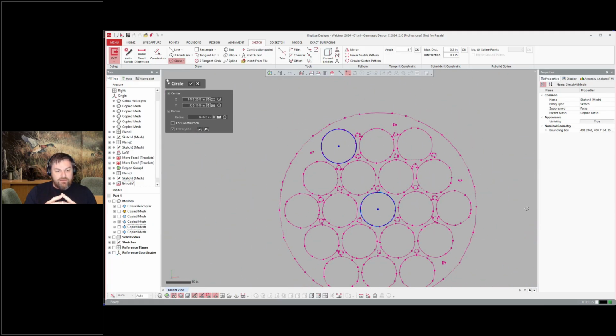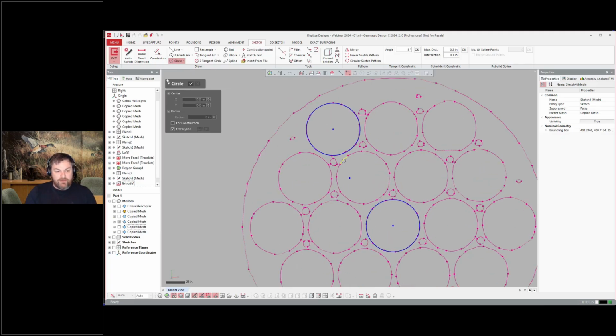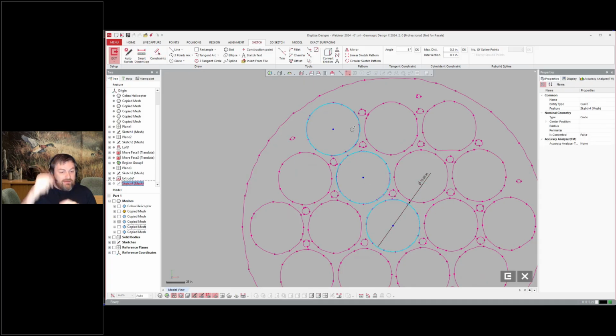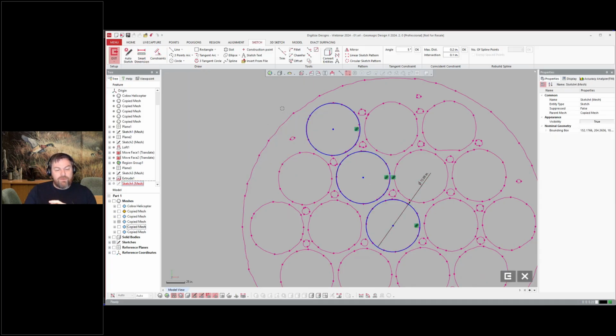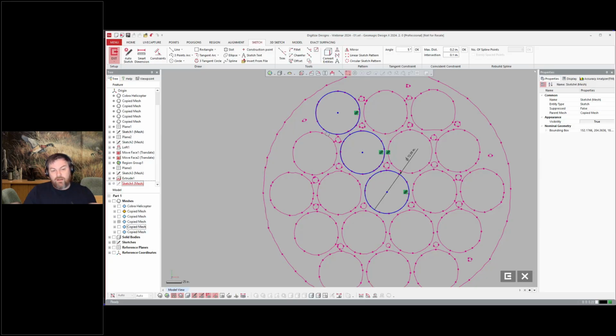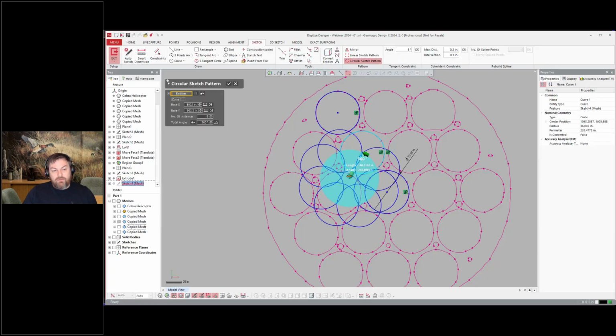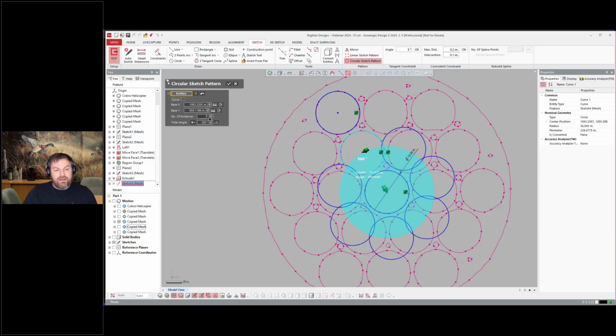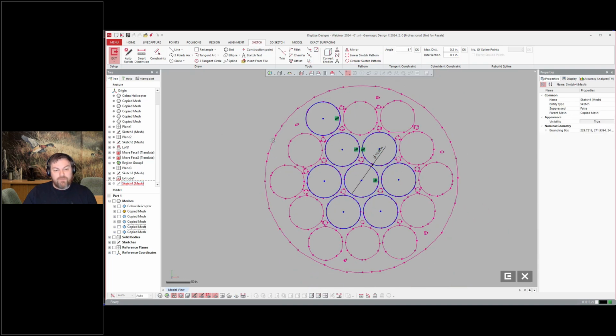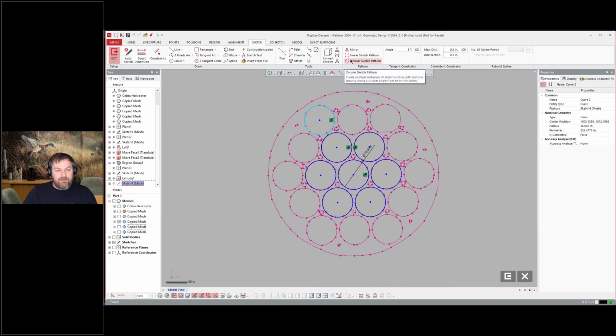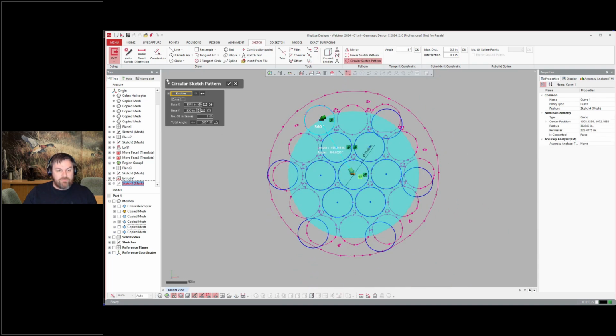Now I click on the end and I say, hey, let's go ahead and model some of these holes. Let's go ahead and model all of them, actually. And I recognize immediately that it's just a pattern, right? So you can say, I want to best fit circle to these. I want to override it to this specific dimension. I want to make them all equal, so they're all equal radius. And then I want to go ahead and say, I want to make this a pattern. So in this instance, I went ahead and patterned them on 3 individual patterns.